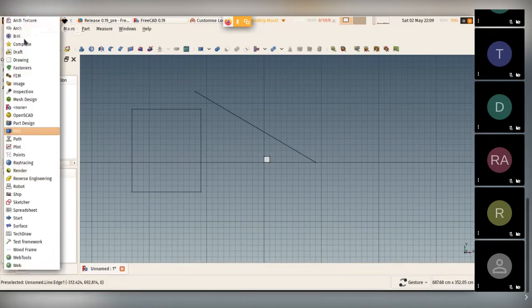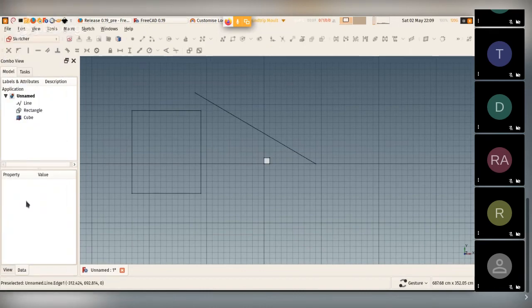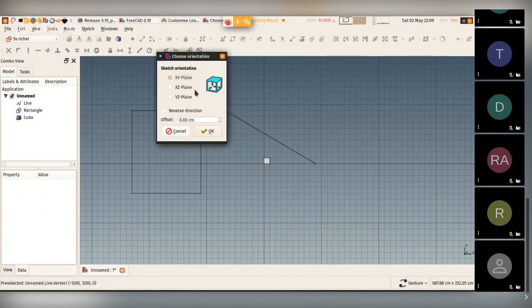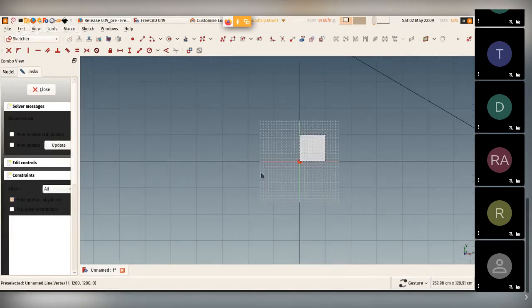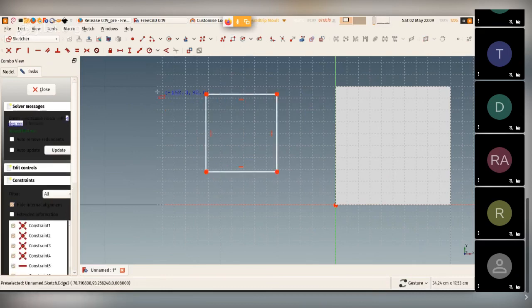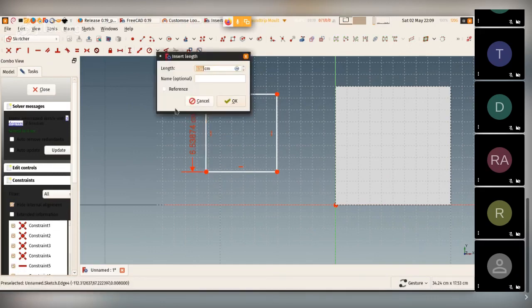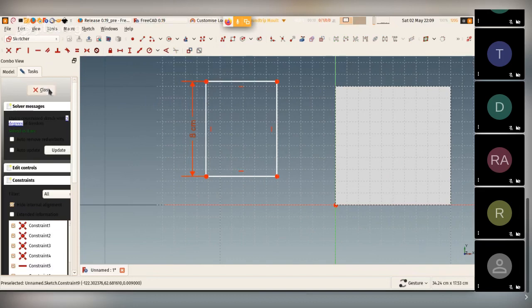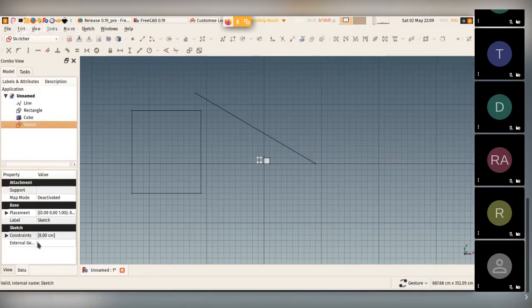And you have this Sketcher that also allows you to do 2D elements, but you can put constraints in it. For example, you draw this, and then you take this and you put a vertical constraint of, let's say, 8. And you can give this a name like height. And then you close, and then this object has a height here that you can change.